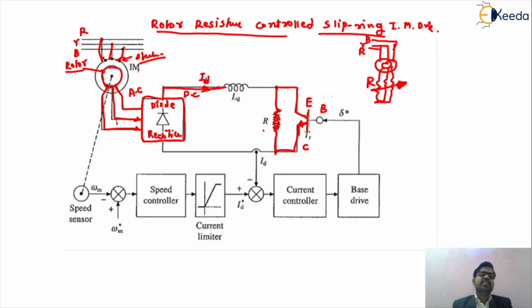Now this DC supply will have a pulsating DC. So we have to filter out this pulsating DC by means of an inductance, connecting a series inductance coil. So this is one type of filter by which we can get the pure DC. So we are getting the pure DC supply by limiting the ripples. So friends, now the resistance is connected. This resistance has the value of R.